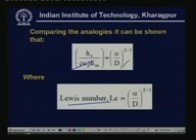So when this is close to 1, then your heat transfer coefficient is nothing but a product of density into specific heat into mass transfer coefficient. So if you know the heat transfer coefficient, directly you can find the mass transfer coefficient. So this is very useful, and we will be applying this when we do the air conditioning calculations.